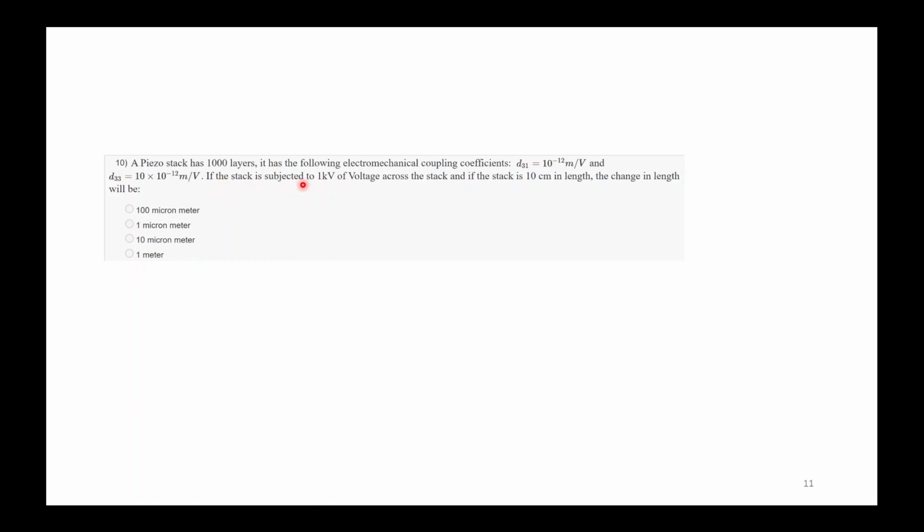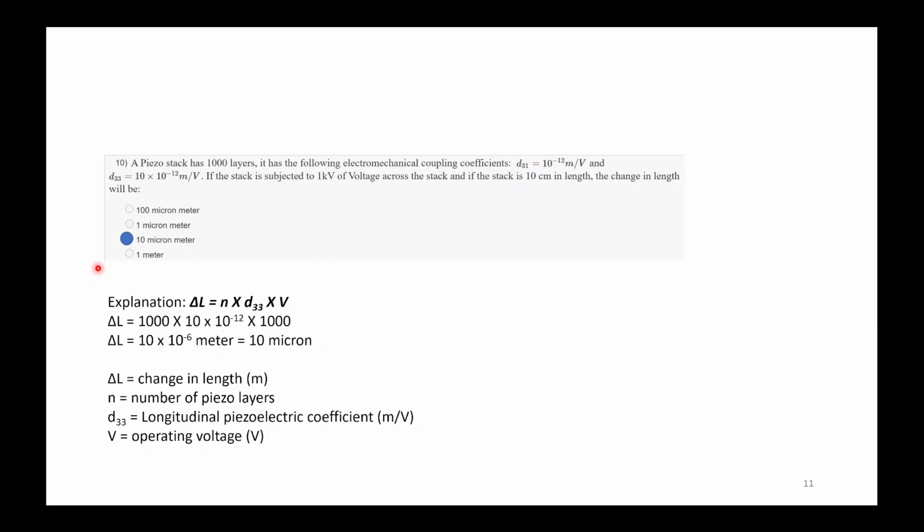If the stack is subjected to 1 kilovolt of voltage across the stack, and the stack is 10 centimeter in length, the change in length will be, options are 100 micrometer, 1 micrometer, 10 micrometer, or 1 meter. Your answer will be 10 micrometer.